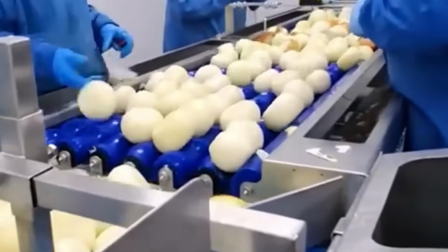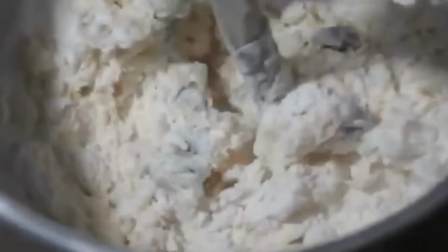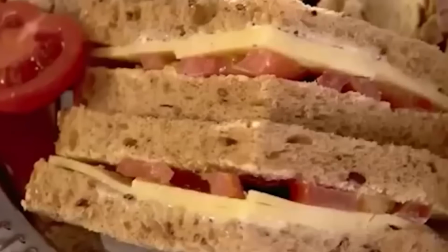If the top slice requires its own spread or condiment layer, a mirrored version of the first spreading station appears here, applying the layer just moments before the slice is joined to the assembled base. The top slice is picked by robotic arms from a secondary line of aligned bread slices, flipped if necessary depending on crust orientation, and gently pressed onto the assembled sandwich with just enough force to compress the stack into a unified structure without squeezing out fillings or deforming the shape.